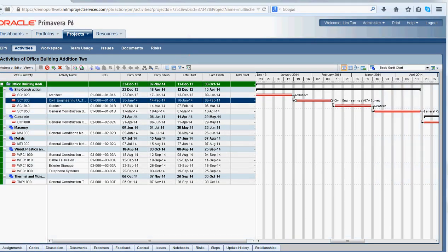There are three things that need to have been set up in order to get the data from P6 to Unifier. Firstly, in the Administer menu, the application settings, so that you can create the P6 to Unifier association.